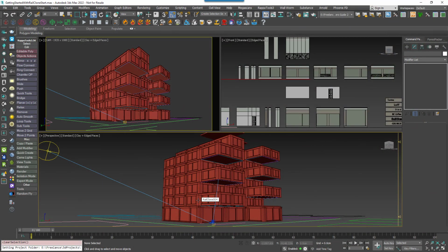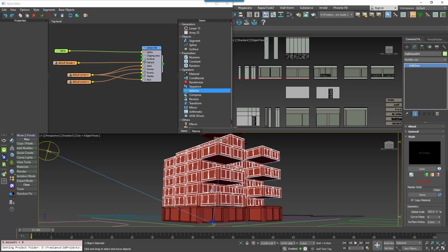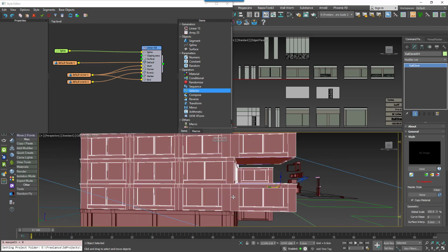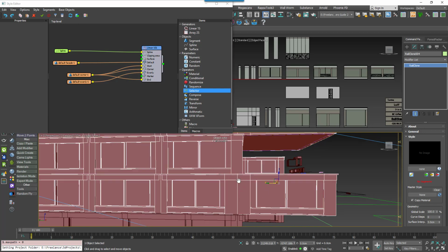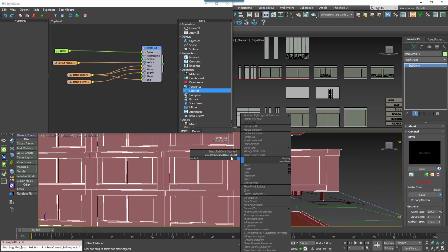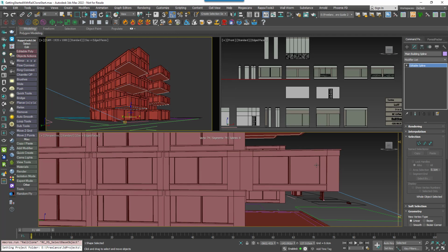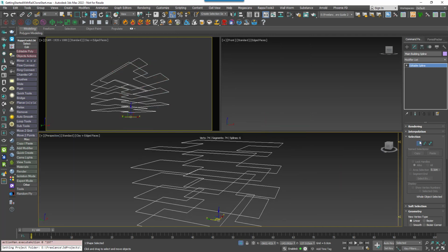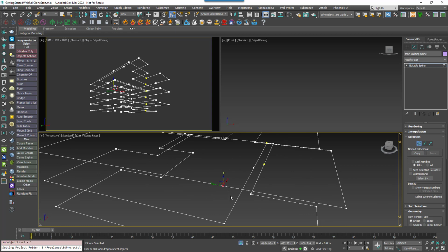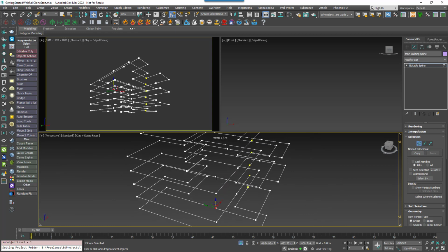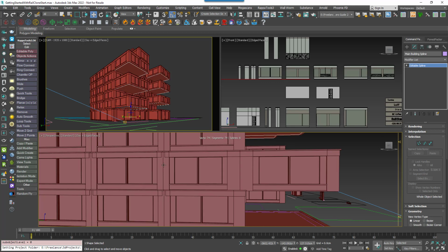So we're going to start with the main part of the building, which currently all has the same segment used. The thing to fix first of all is this pilaster here, which you can see is double the width of the one above and below. This is because it's on a corner, and if we go into the spline we can see there's a corner on a straight section of the path. If you remember from a couple of tutorials ago, corners work by putting a whole segment either side of the vertex, and that's why we have a double thickness here as opposed to the 90-degree corners.